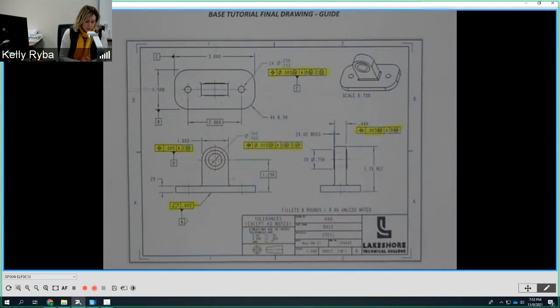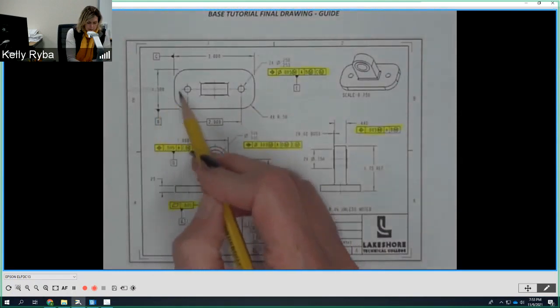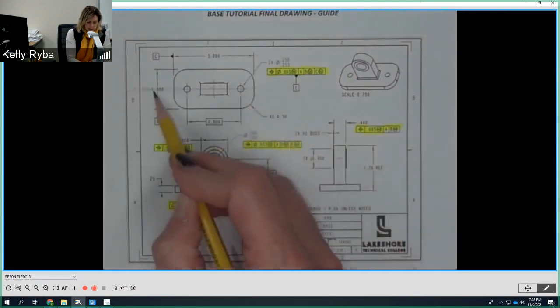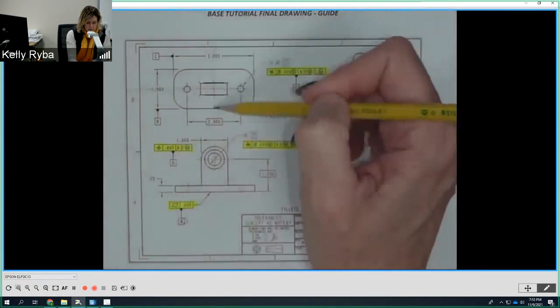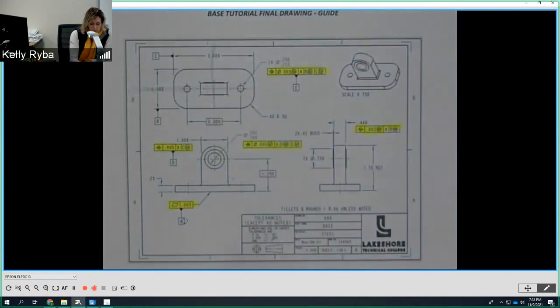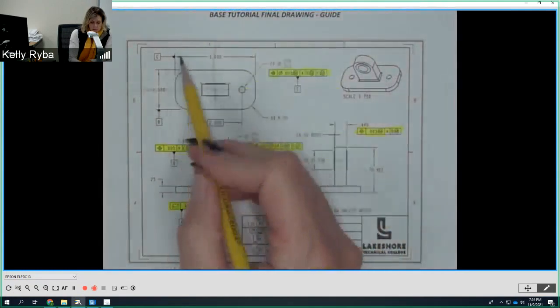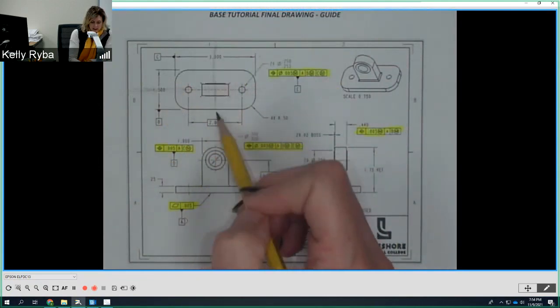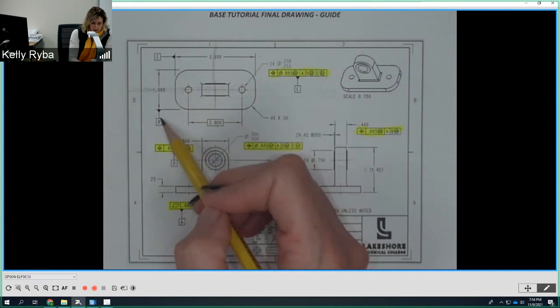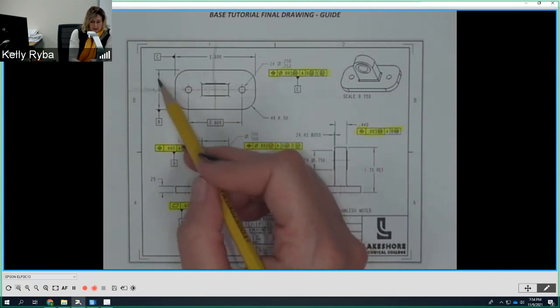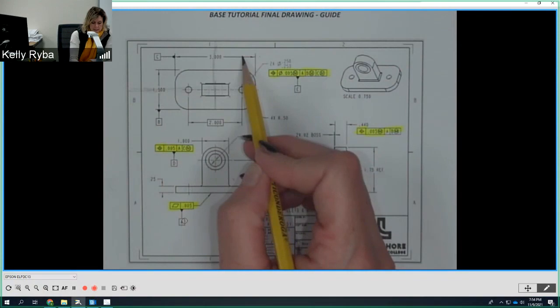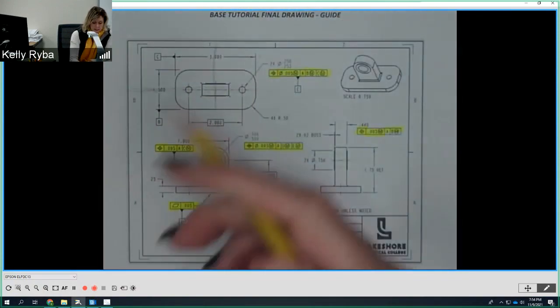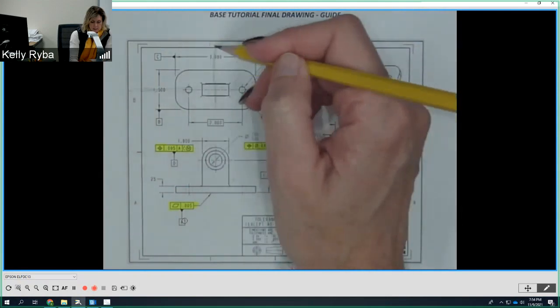So to do that, what we want to do is establish those center planes of those non-cylindrical features, so that there's a center plane about this dimension here, the 1.5, and there's a center plane about this dimension here. And to do that, we don't want to go from the sides of the part, the surfaces. We want to put our datums in line with the dimensions, and then they default to the axes, okay? So datum C and datum B are in line with the height and that length dimension, okay? And that means that our datum is defaulting not to the surface, it's defaulting to the center plane, okay?